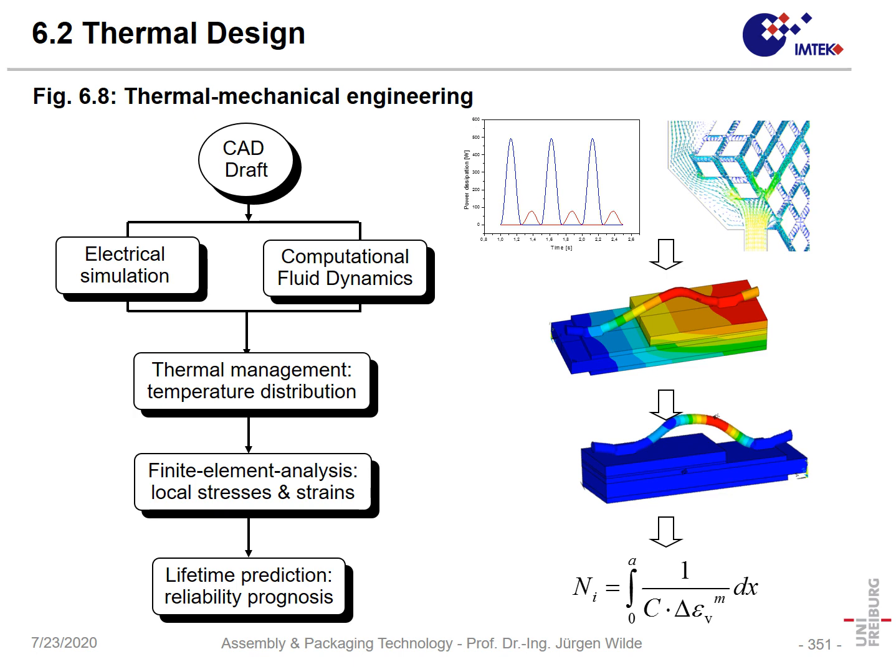So for instance, that was for an electro vehicle which just started to drive. So the frequency is very low. That's in the IGBT and that's in the diode. And in that way, the power dissipation can be estimated. It's not so easy because power dissipation, again, is dependent on the temperature. But now, let's assume we have a first estimate. The second is not only the power dissipation, but it's also the cooling.